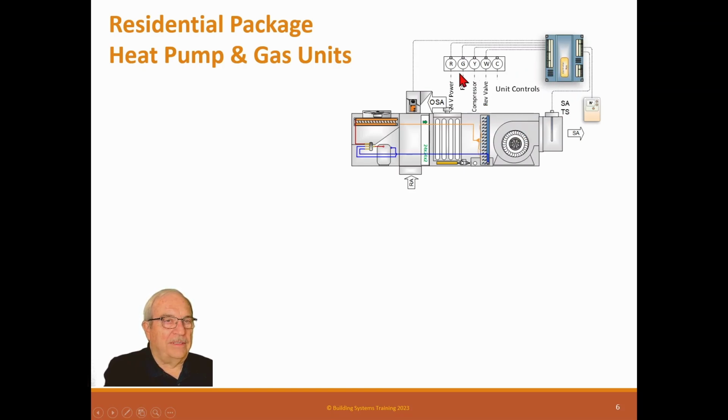So we have on a controller, again, a room sensor and a discharge air sensor. And the reason we use these discharge air sensors is for unit status. They're really cheap. $60, $70 will get you a supply air temperature sensor, and it'll tell you anything that might be wrong. It won't tell you exactly what, but it'll tell you it's not working.